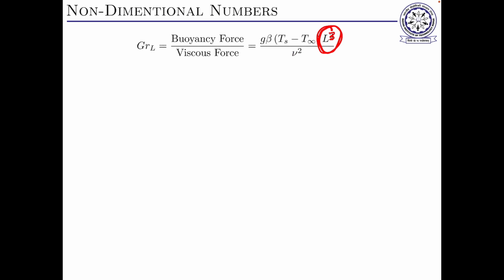This shows what I initially said: the taller the system, the more effective it is, because the Nusselt number for natural convection turns out to be a function of the Grashof number and the Prandtl number, and the length is raised to the third power. If the system has a much higher height, then it would be more effective.